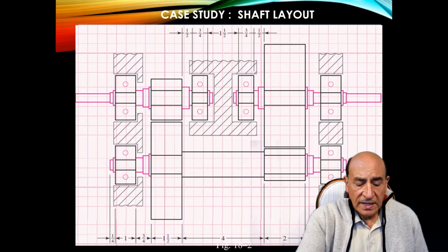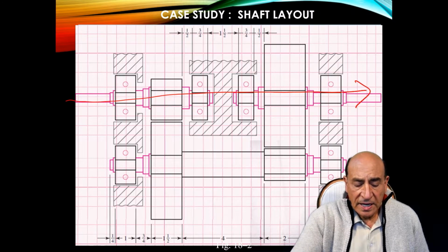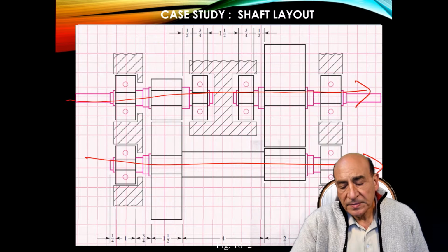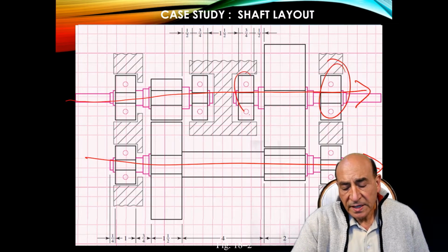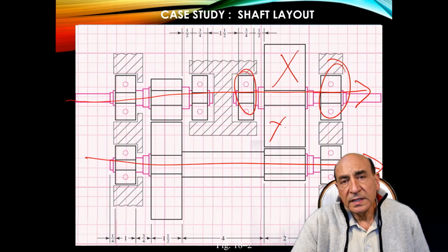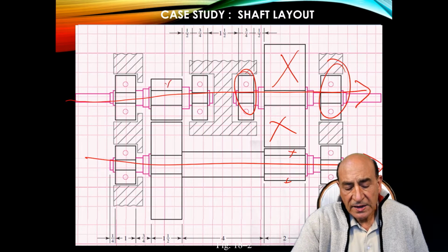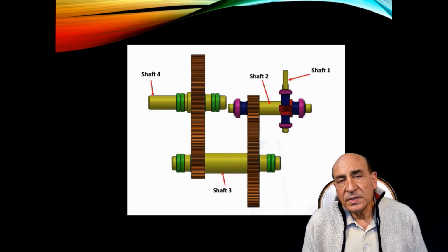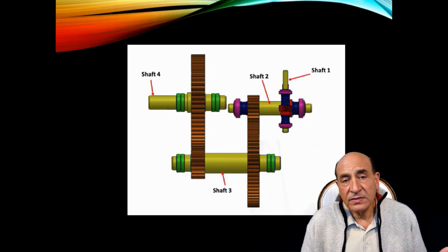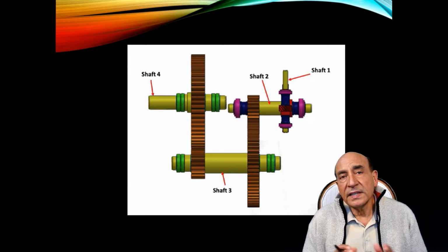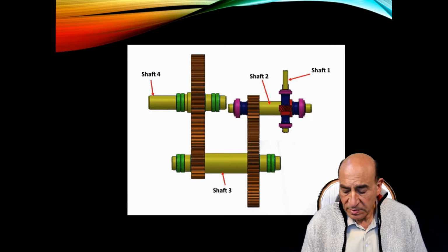So you have an input shaft here and an output shaft, and here's a bearing, and then this is the gear, and this is another gear, the main gear, and so on. So you have all of the gears. That's how you would make the shaft layout. This is just for 2 parallel shafts, but your design could have several shafts, and some of them could be at 90 degrees, making it interesting to lay it out in the minimum volume possible for the gearbox.